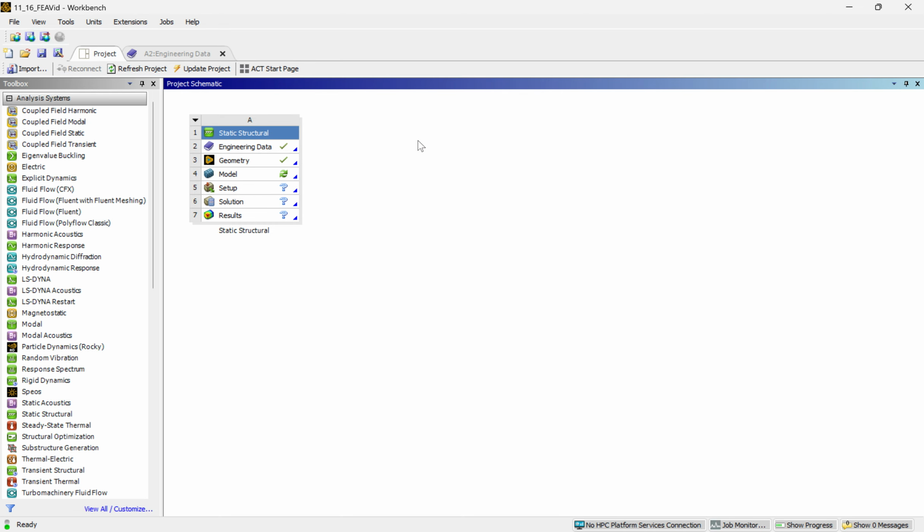And as you can see, the geometry box is now clicked. So the way ANSYS works is it has all these kind of substituent programs like SpaceClaim and Mechanical and ACP, but basically it's all tied back to your Workbench. So when you update one, the other should also update. If it's not, you can click the update button and then it'll make sure to transfer everything. So that's a good thing to do if you're ever unsure that your changes transferred. But yeah, it's kind of cool how it works like that.